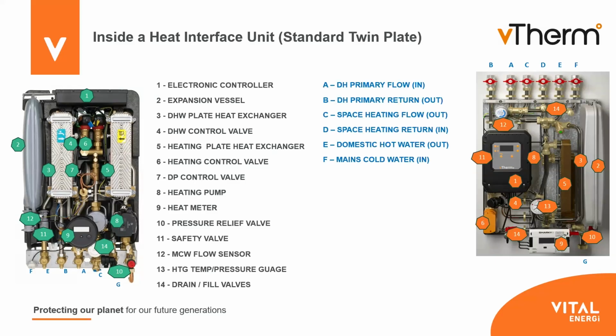Very quickly, we've then got the primary circuit, flow and return, your CH or your space heating pipework, flow and return, your mains cold water coming in, maximum of 10 bar, and your domestic hot water, hopefully nice hot water, flowing back out. And then, as I've mentioned before, the safety relief valve discharge pipe.